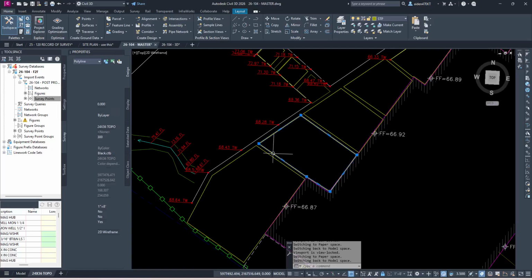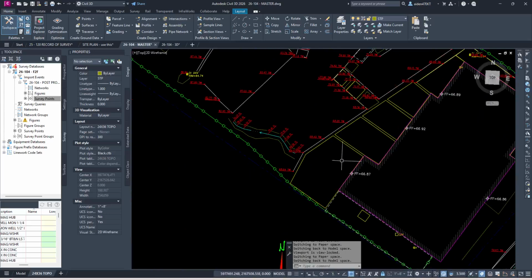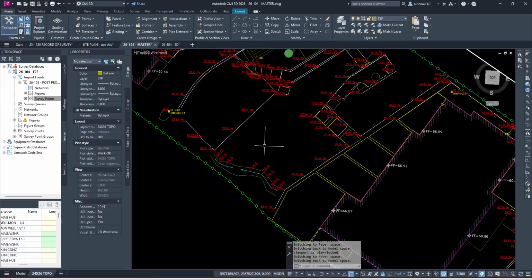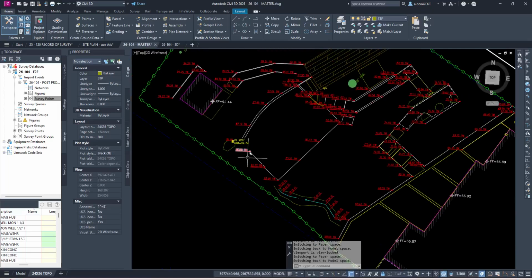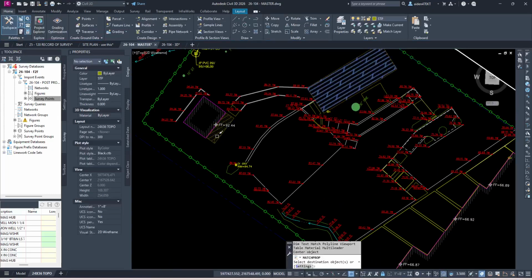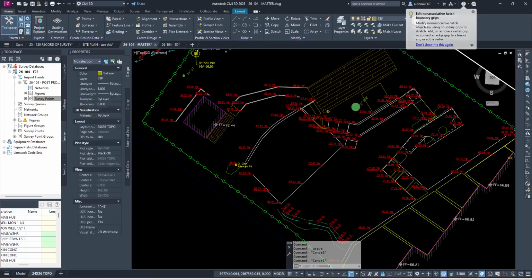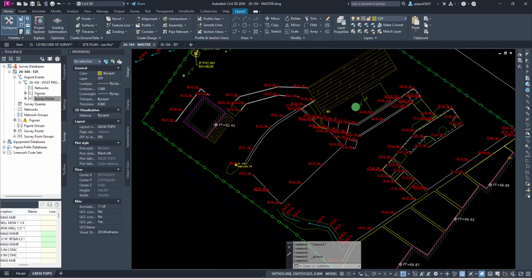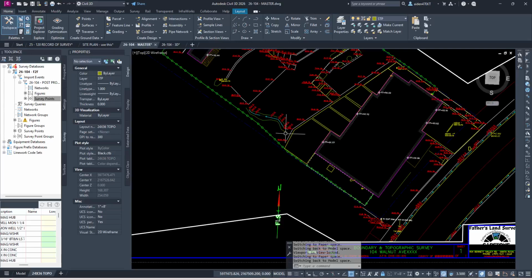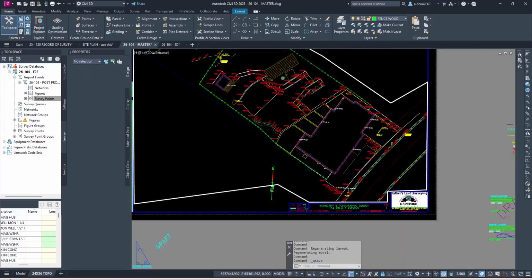Hatch, and then we could probably hatch the concrete. It looks a lot better. You don't really have to, it just looks better on the map. Looks like these are little concrete blocks. Let's hatch this deck again, or we can just match properties, make it easy. It's a smaller deck, so maybe I'll rotate it and reduce the scale to 3. And then you can do line type generation, makes everything nice and consistent.